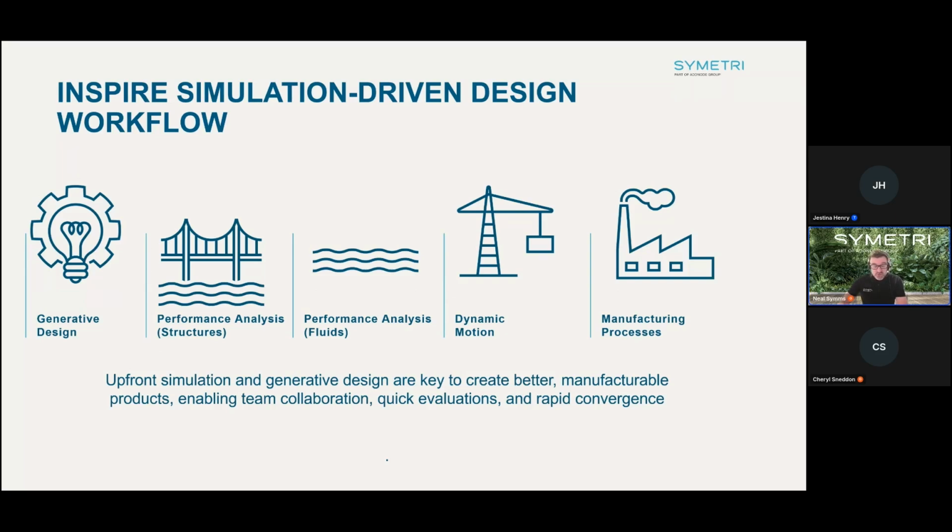Performance analysis for both structures and fluids. Once initial design concepts are generated, structural simulations are performed to evaluate the performance under variable loads and conditions. Inspire's structural analysis capabilities enable engineers to predict stress, strain, and deformation, ensuring the design meets strength and durability requirements. And the same applies for fluids. For any applications involving fluid flow, such as aerodynamics or fluid cooling, Inspire's CFD, or computational fluid dynamics, tools are used to analyze fluid behavior, and this helps us optimize designs for factors like drag, lift, or heat transfer.